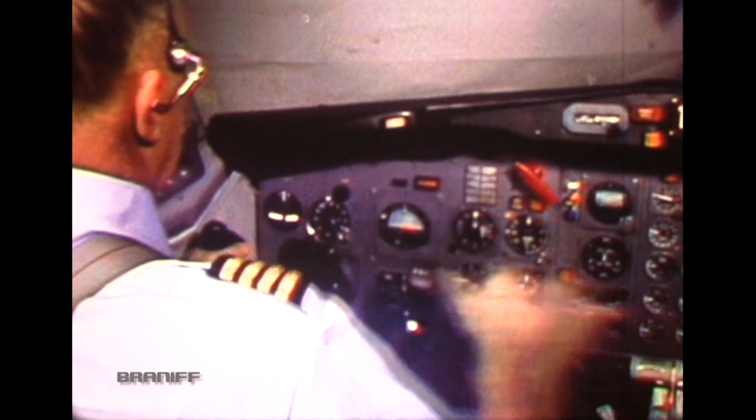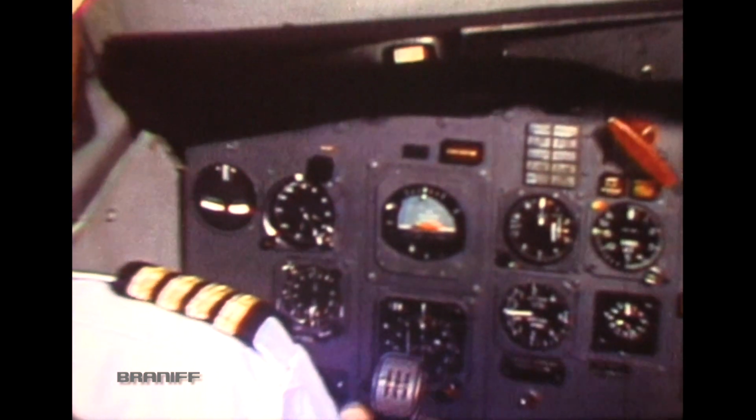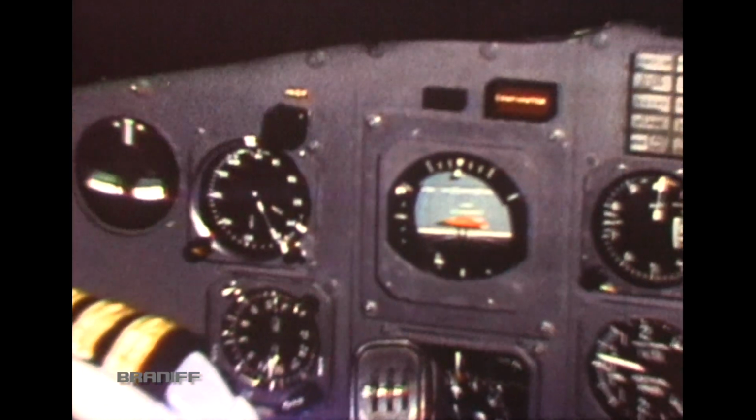Crosswind directional control during the initial takeoff roll may be reduced, particularly for light gross weight and aft CG conditions. Use caution not to oversteer the nose gear. Use rudder pedal steering for corrections to centerline. At VR, rotate the airplane smoothly at a normal rate, approximately 3 degrees per second.